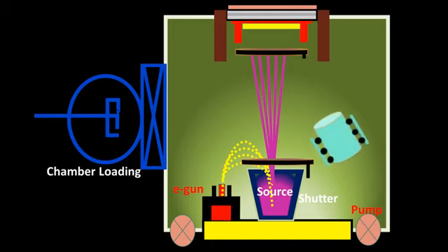Now the question here, student, is that usually in an MBE system they use different kinds of dopant. The thin film fabricated by molecular beam epitaxy can have a wide range of dopants. If we want to prepare P and N type doping using molecular beam epitaxy, there is a setup based on an effusion cell, which is used to introduce a dopant onto the surface of the substrate.